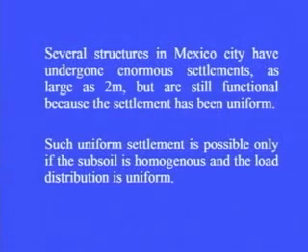Several structures in Mexico City have undergone enormous settlements of the order of as large as 2 meters, but are still functional because the settlement has been uniform. Such uniform settlement is possible only if the subsoil is homogeneous and the load distribution is uniform.